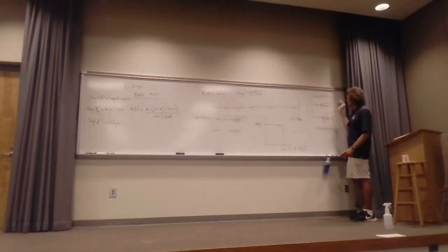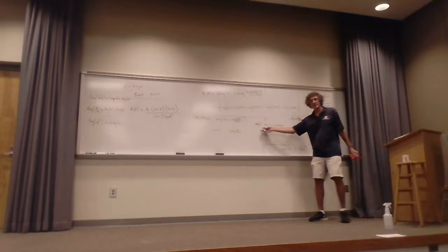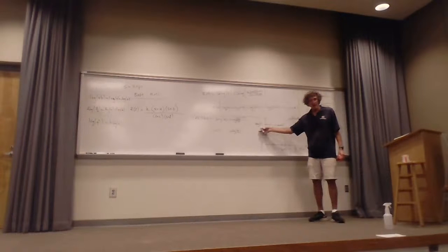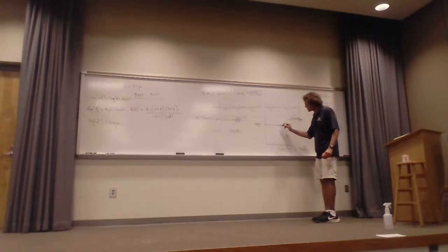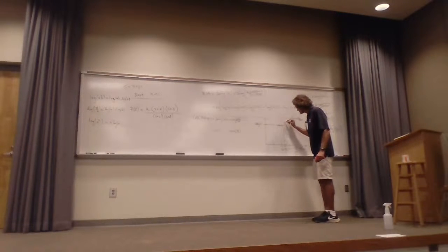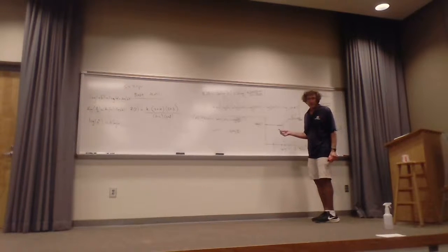But remember, there are two ways of doing this. You can come up with this part. Y'all see this? Then you can say as omega is very small, you get 20 times the log of, well, it's just the square root of A squared, which is A, so 20 times the log of A. Same thing as I got here. Y'all follow me? And where all of a sudden that changes is when omega equals A, then it starts going up by 20 dB per decade. Now the real truth is if you look at an exact plot of this, you'll see it curved like this, and there will be a 3 dB difference between the actual value and the approximate value. We always use straight line approximations in engineering to show this, so it's real clear. With me?